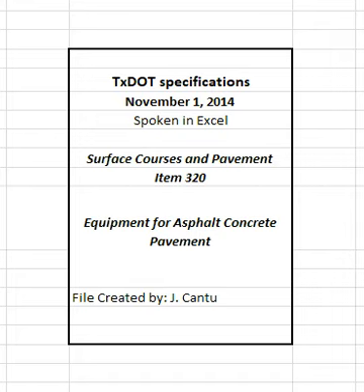2.3.1.3 Grade reference. Provide a grade reference with enough support that the maximum deflection does not exceed 1/16 inches between supports. Ensure that the longitudinal controls can operate from any longitudinal grade reference including a string line, ski, mobile reference, or joint matching shoes.